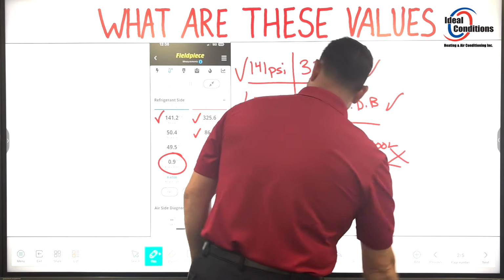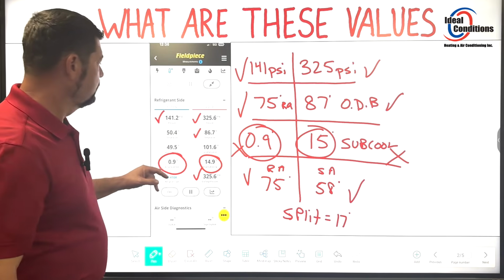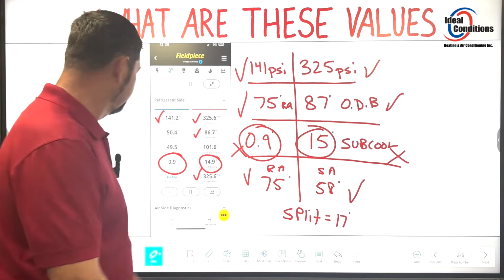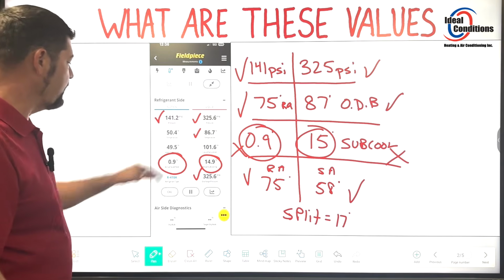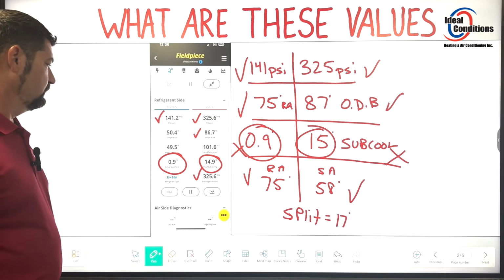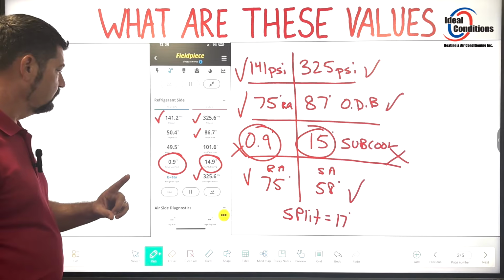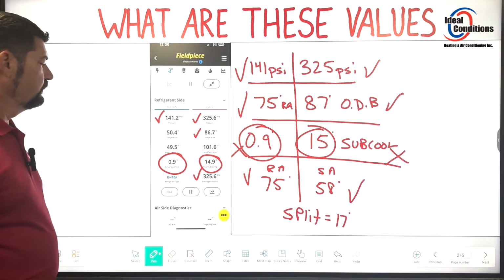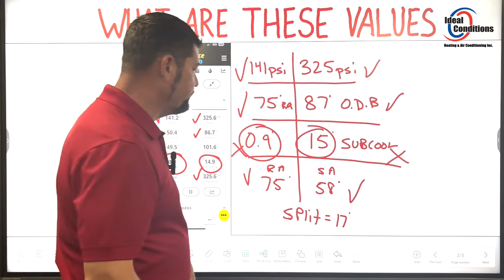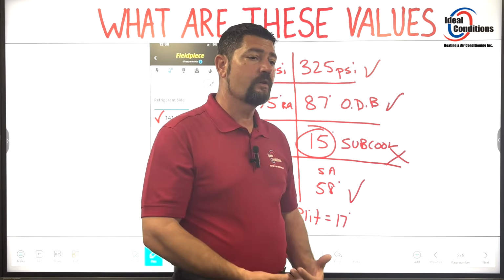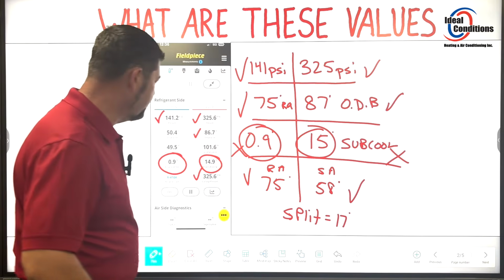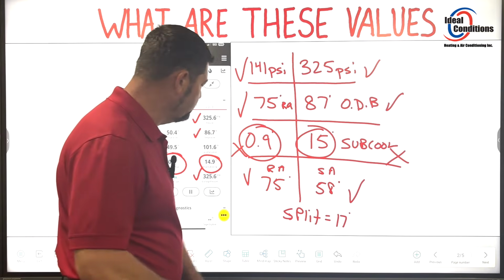All right. Let's go back. Looks like we're not in range. There's too much refrigerant in the system. Let's pull some Freon out. Or is there something else going on? So the first course of action would be the one that makes the most sense. Let's go ahead and do a charge adjust. Maybe we'll get that recovery tank out of there, open up that high side, squeeze some refrigerant inside of there.